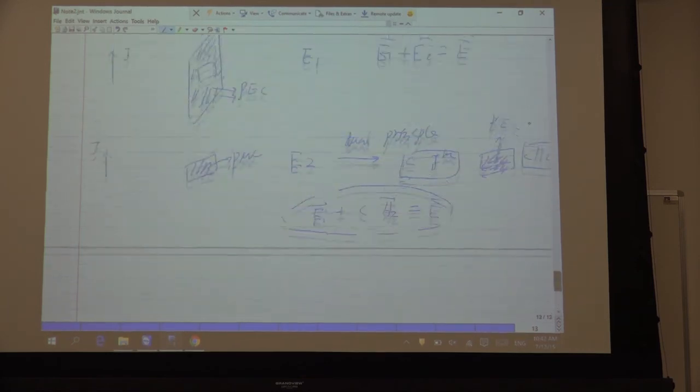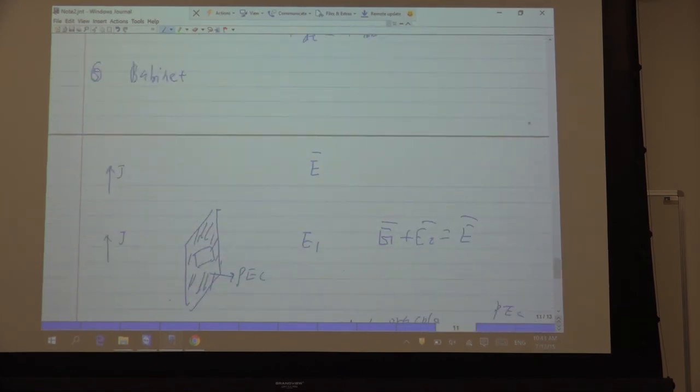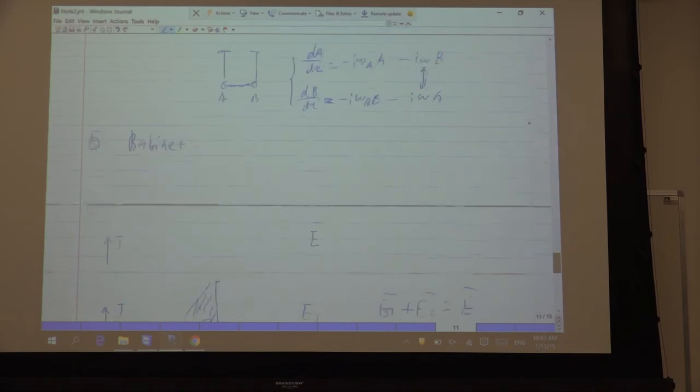With the Babinet principle, we know that, I give an example for this metasurface. If we have a PEC loop, it is similar to a magnetic dipole, this M, because it's a current here, Ampere's law, a magnetic dipole. So if I use this PEC, I give a slot. This slot is a complementary structure. This is similar to the electric dipole. You can use the Babinet principle to understand many things. This is all the five theorems in the first chapter.